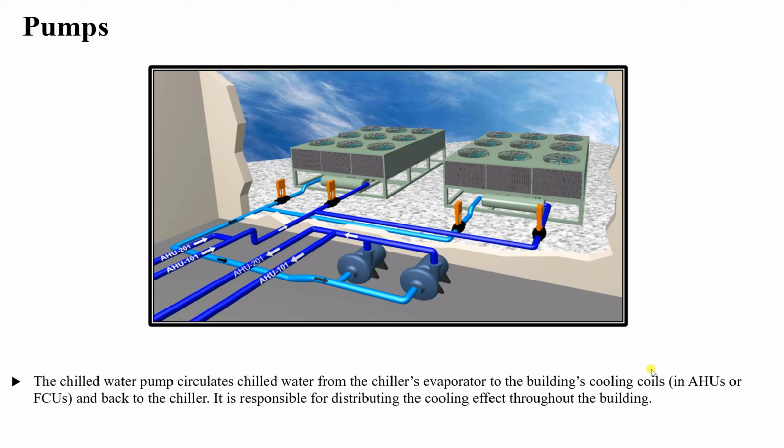And remember, since we have pumps here, we need to design either an MCC, or a motor control center, that can be used to control these pumps, or design a disconnect switch for each pump. Okay, but usually these are put on one big panel for controlling the motors. These are usually, of course, located near our chiller.